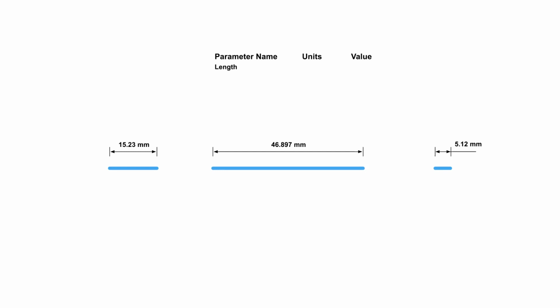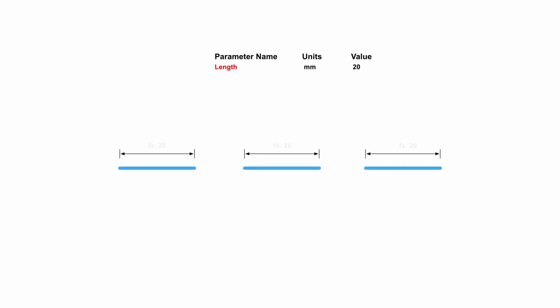In this video, you will learn how to use sketch parameters to drive a parametric design in Fusion 360. Parameters are a powerful toolset that can be used to drive and edit multiple dimensions from one single named parameter. You can create predefined parameters with a value, then assign that one parameter to multiple dimensions, as opposed to individually